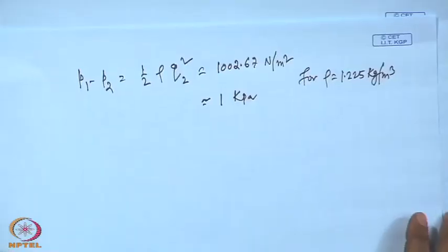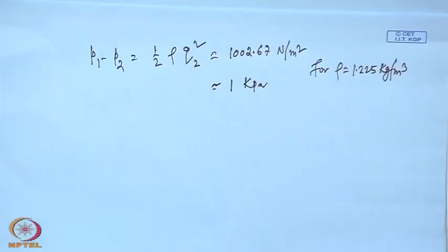So, with this we will conclude our discussion on this conformal transformation or the transformation technique, but two things I will just ask you to do. If you can't, we can discuss it later. I will ask you to find the moment coefficient; the lift coefficient we have found for Joukowsky airfoil. I will ask you to find the pitching moment coefficient and the aerodynamic center.